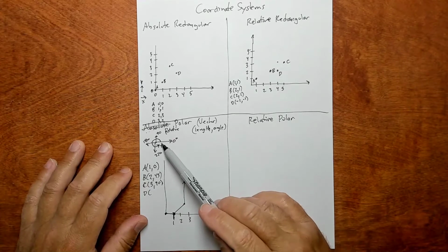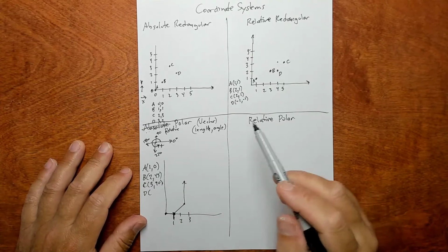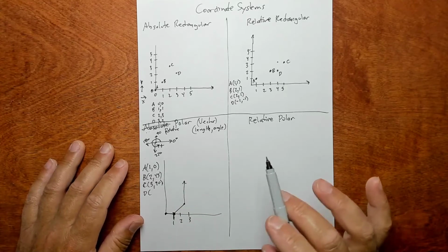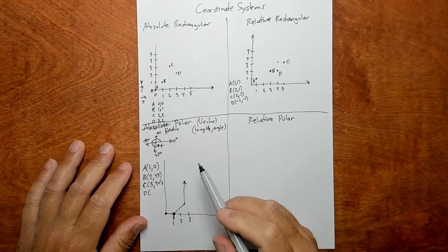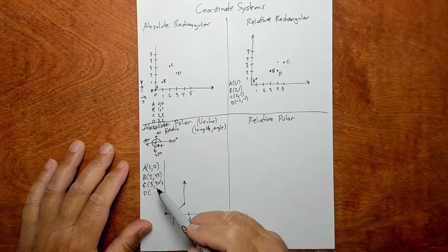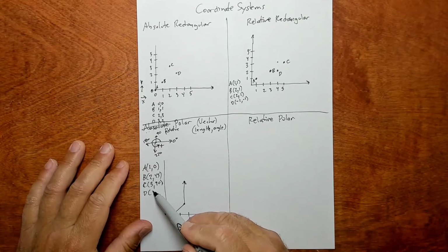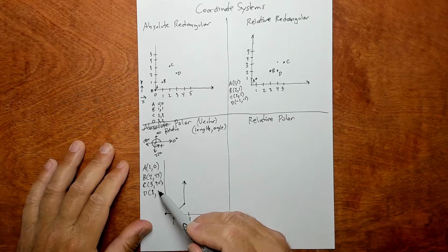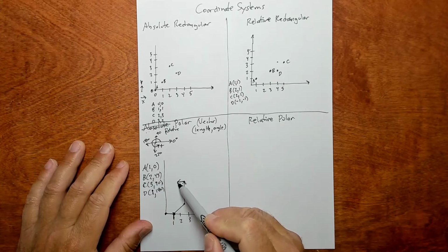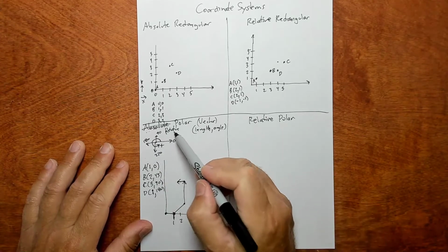It's a little tricky because the way that you enter angles in AutoCAD is always absolute, but the way you interpret a series of angles, you could interpret 2 different ways. So I think that's a little confusing. Hopefully that'll become clear when you're doing the homework, and let me try and clear that up a little bit now. But anyway, let's do one more angle: 1 and 180. So I'd go back 1. I go a length of 1 with 180 direction that way. Okay, so this was relative.